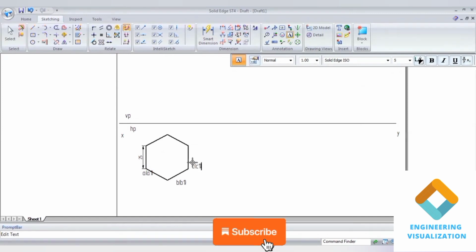So here we need to find the center of the hexagonal prism. For that at least one or two lines need to be drawn, because since it is a prism, to find the center of the axis there is no need to draw all the lines. Inside this hexagon we should draw thin lines, not thick lines.